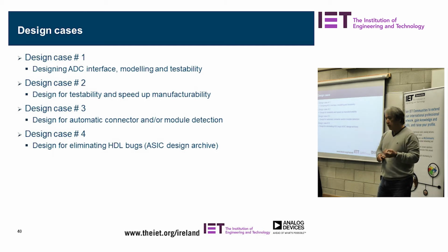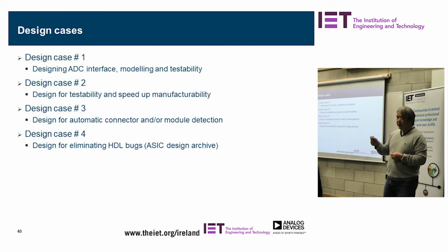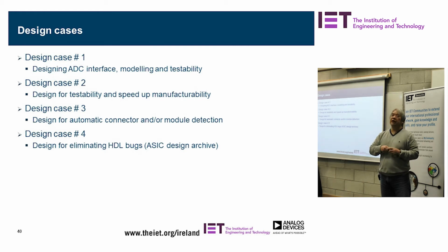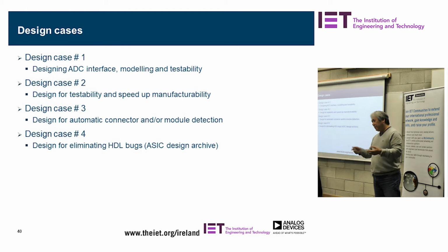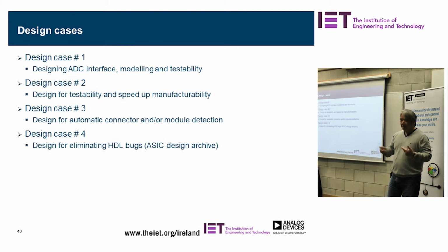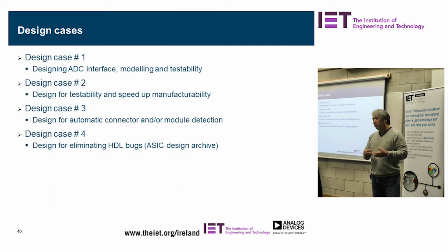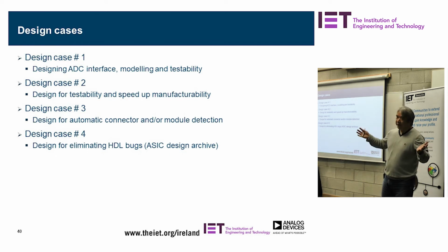So I looked at the design, it looks okay. I looked at the layout, the layout looks good, so I asked them for a timing plot. And with the timing plot, I said to them, look, it's an easy fix for you. That clock, just invert the clock and it should be okay. And he looked at me as if I had two heads. I said, we spent 3 weeks at this. And he said, you tell me just invert the clock and it works? I said, yeah, try it. So eventually I persuaded him, he tried it out and it worked first time.